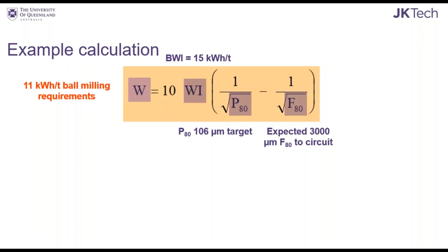It must be noted, though, that the power requirement calculated here is the mill pinion power. So there is energy loss between the pinion and the actual motor that does need to be taken into consideration in any of your design calculations. So that's for design requirements.